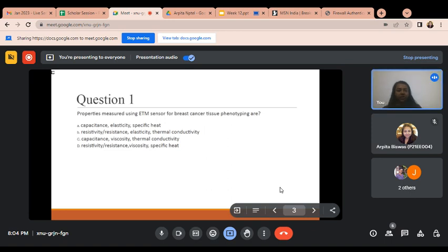So what happens in the isotropic etching process: if there is a device and a surface material is present, and we dip this wafer into some etchant solution, if it is isotropic, then in all directions it will etch the wafer the same way. But if it is an anisotropic process, it will etch in a particular direction.